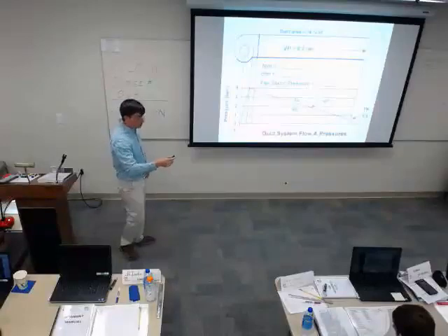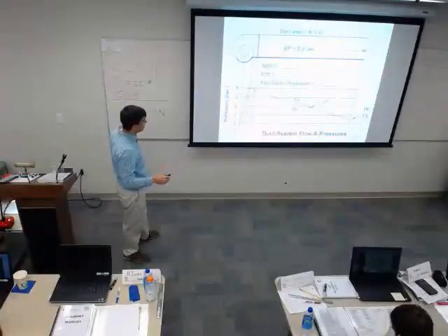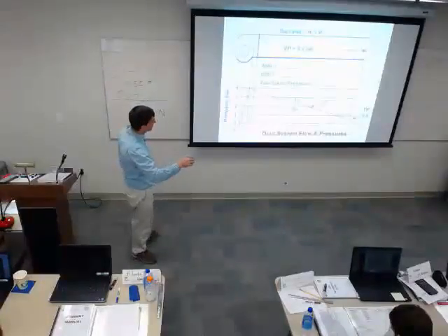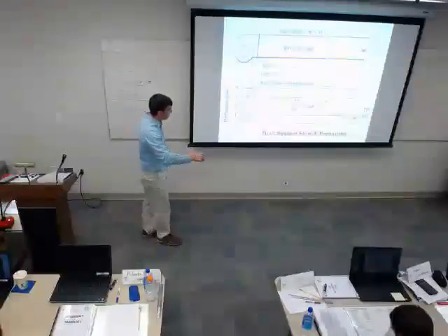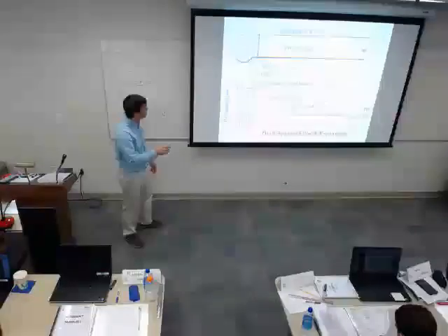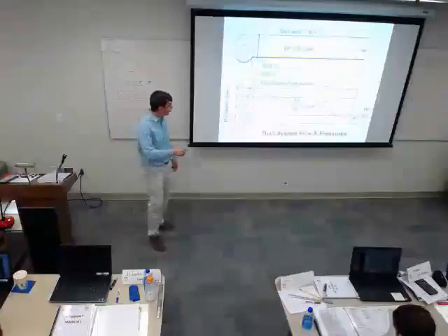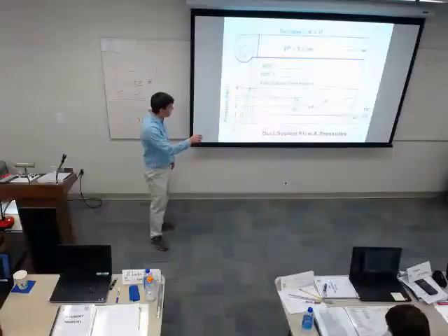All right, so on this image, I've got a fan and I've got a piece of duct attached to it. Don't look ahead in your book, I wanted to see if y'all can remember how to do this problem. I'm looking at pressure on this axis and just the length of the duct on this axis. So on the inlet of my fan, I would probably measure a negative pressure, like a negative 1/2 inch. That fan's job is to raise that pressure up, and if I'm looking at static pressure, I've got about 3.5 inches of static pressure.